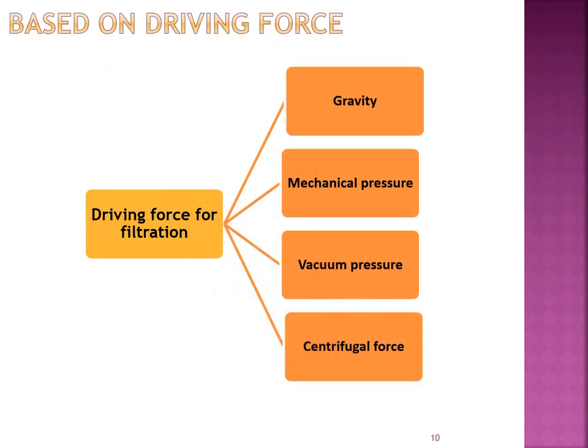Based on the driving force of the filtration, how can we separate the solid from a liquid by using a filter medium? First, this driving force can be gravity. When we pour a fluid on the filter medium, the solids are retained and the liquid percolates through the filter medium and is collected as a filtrate.